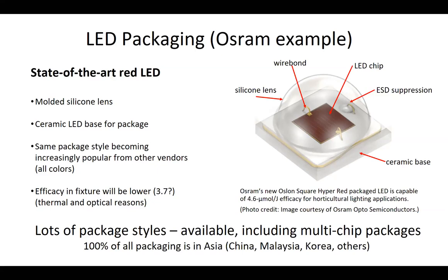Yeah, and I think just to add a little bit to this, greenhouses have a very variable lighting condition. If you rely on the sun, you can have cloudy days, rainy days, very sunny days. Then you have your controllers on CO2, temperature. You have people across the US who grow different crops. So I think LEDs allow us to have a much more flexible design for a lighting system than an HPS light or HID lights, the metal halide lights as well. Yeah, I think that we can really build on that.